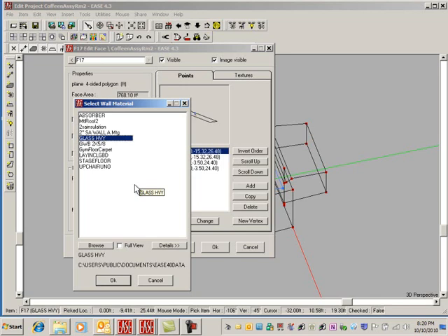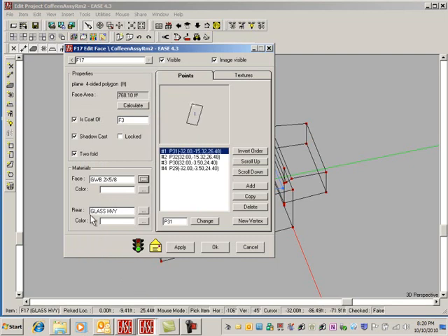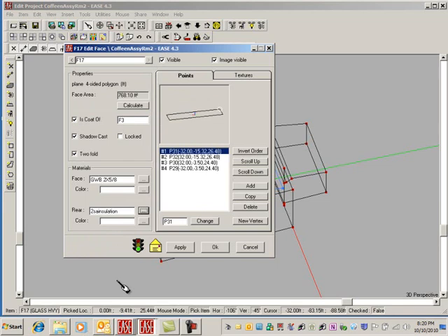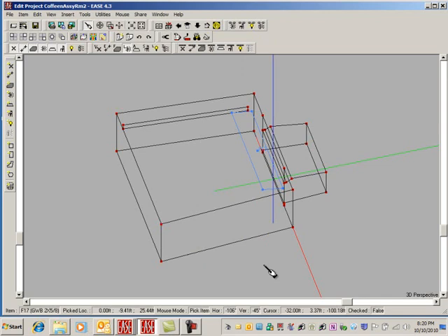Now we have one panel. Now the next panel is identical to it, 12 feet, the same distance, but it is 13 feet into the room from the first panel, according to the section. I could simply select this, do a right mouse click and say duplicate it, minus 13 feet in the Y direction, and Z0, X0, say OK. Oh, there's our second panel.